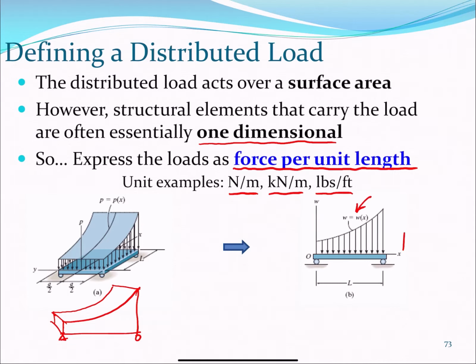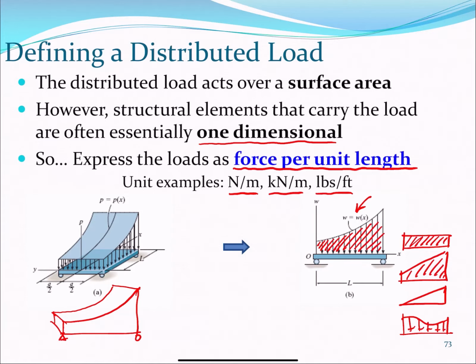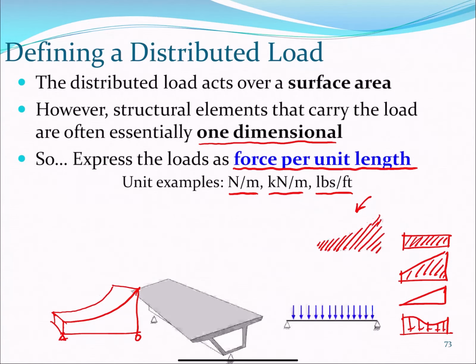In some cases, we may be given a function to describe the loads. Not only simple things as a rectangle, or a trapezoid, or even a triangle, but sometimes they may even give us some sort of variation. The load may actually follow a specific equation. And you know that if we calculated the area in the past for these two shapes, now you see it coming, now is the point in which I will ask you to use a bit of calculus to find the area of that shape. So that's where the calculus will come into play.